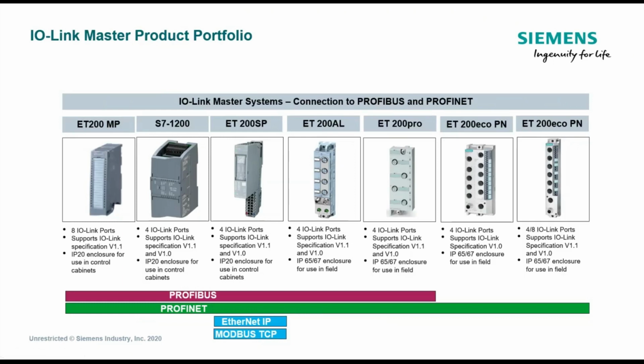Any more? One more came in. SIRIUS ACT is supposed to allow multiple lighted buttons with just a ribbon cable between them. Is that not supported with IO-Link? No, the ribbon cable connection for the SIRIUS ACT line is a Profinet solution. So you'll have a front-end interface that will connect to Profinet as either a standard interface or a fail-safe interface. And off of that interface, you can have 20 additional operators that are connected via that ribbon cable.